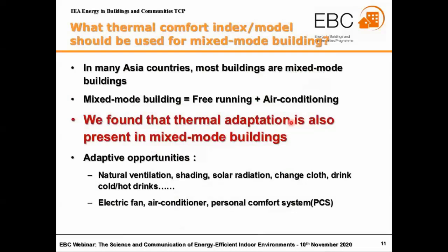Just as we mentioned the air conditioning building and the free running building, how about the mixed mode building? Because in many Asian countries, most buildings are mixed mode buildings. What is a mixed mode building? It means free running plus air conditioning. In this kind of building, we have more adaptive opportunities, including natural ventilation, shading, solar radiation, changing clothes, drinking cold drinks, and facilities including electric fans, individual control air conditioners, and personal control systems.